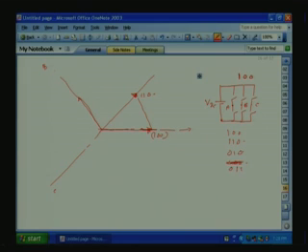That means B and C are VDC. Take the vector sum. It will be along the negative of the A phase axis, because B plus C is equal to minus A. So the vector is here, and this is also VDC, so here it will come, minus VDC.